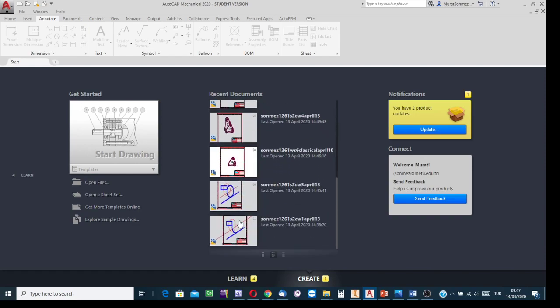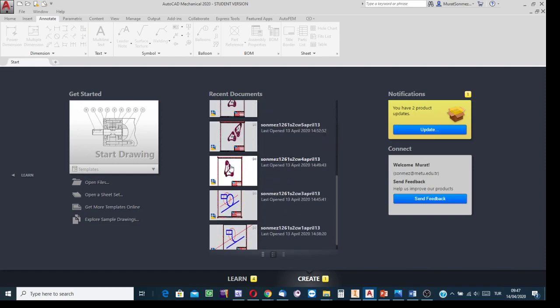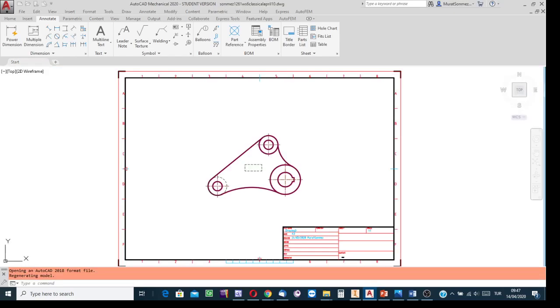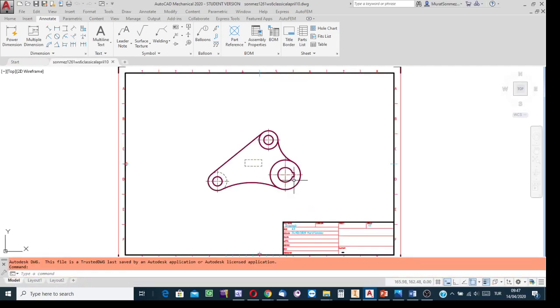First thing to do is that, here is the AutoCAD file, and I'm going to use this projection in Inventor as the region, as the necessary profile. It has been drafted in the AutoCAD environment. It is ready to import, to export.